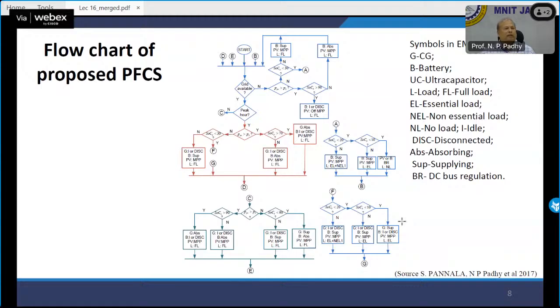So the state of microgrid components matters. First of all, you check the grid position, whether it is peak, off peak or islanded. Depending upon these three, you check whether your PV is more than load or less than load. And then based on the battery conditions, 30 to 70, 10 to 40, 20 to 90, whatever the conditions, you take an action. And this is known as energy management. Basically, you are managing the energy requirement of the whole system.